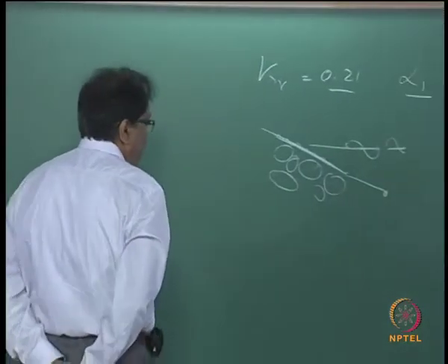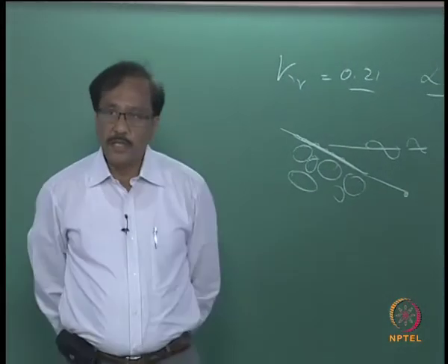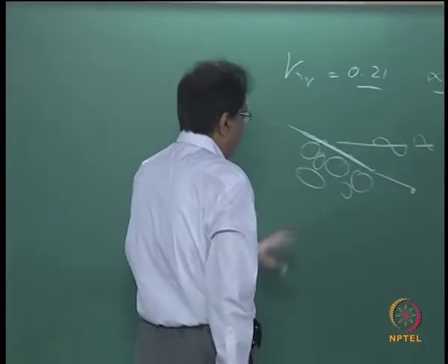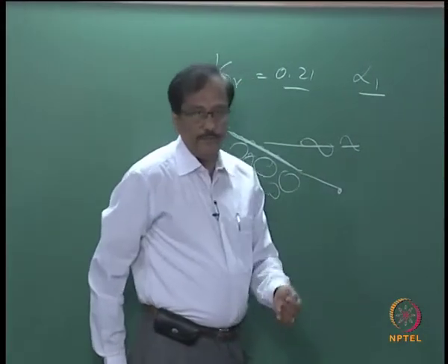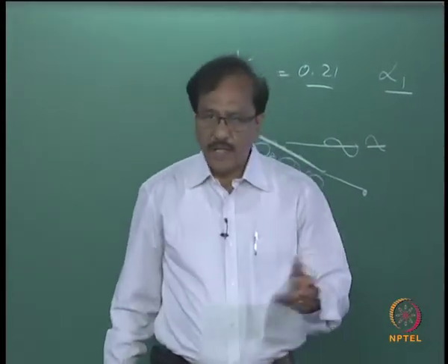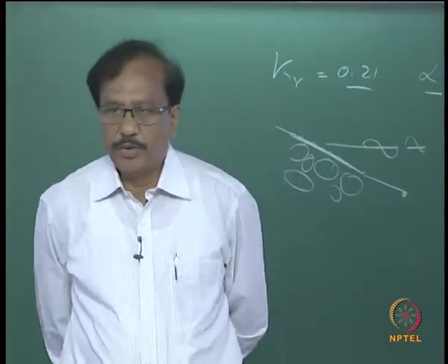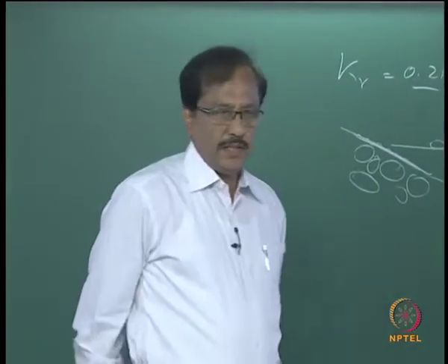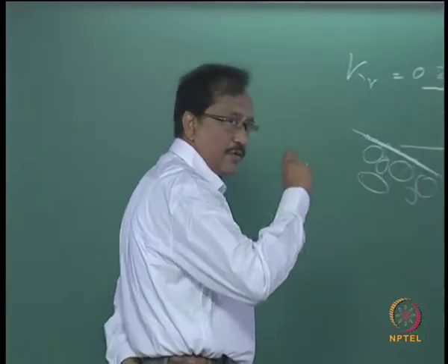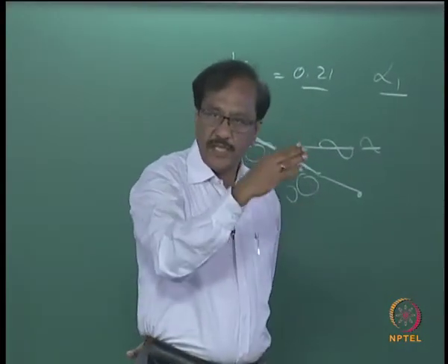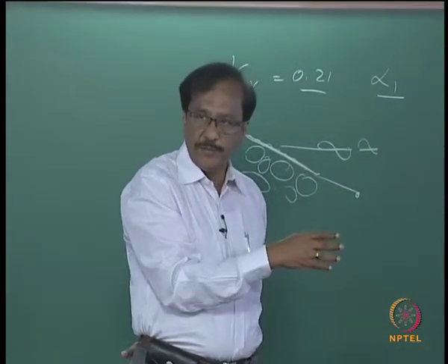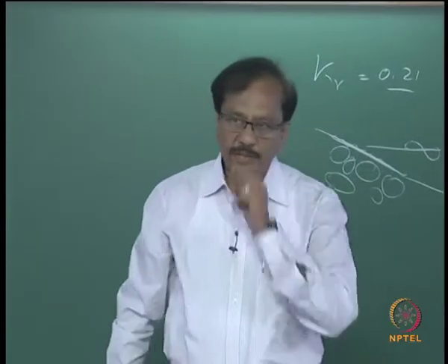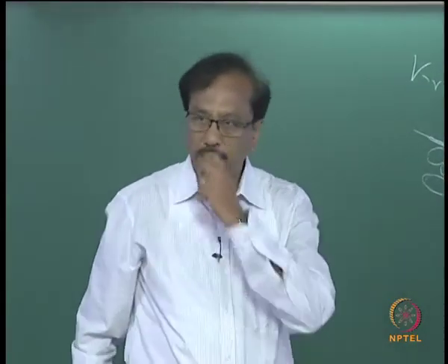Later when we discuss the chapter on breakwaters, we will see how these multiple layers are going to be effective, but I have already highlighted the multiple layers earlier, that the bigger size stones will be on the surface, and as you go towards the core of the breakwater, the permeability or the size of the stones will reduce, okay.